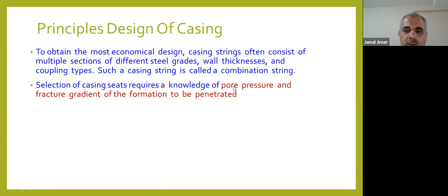So once we determine the pore pressure and fracture gradient, we have to apply a margin. We call it margin for pore pressure and fracture gradient. So we continue our drilling in between these two margins.